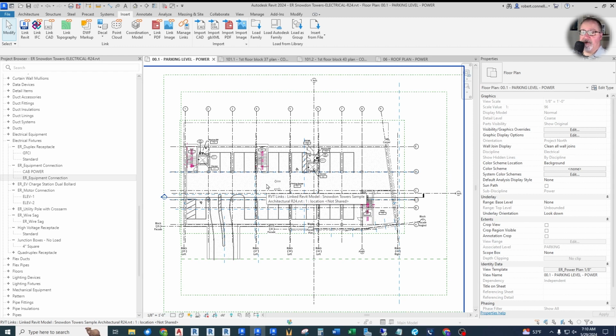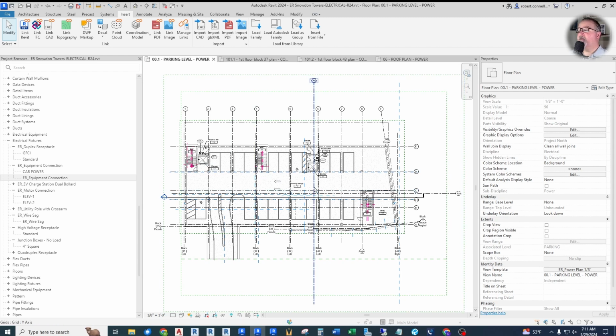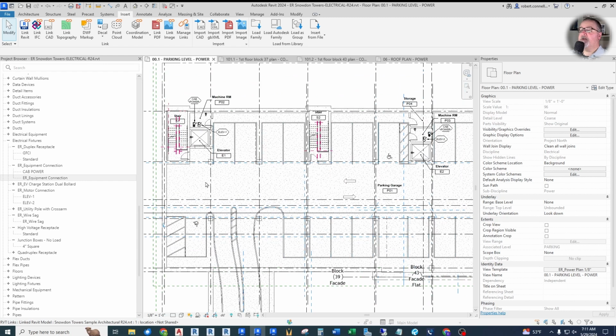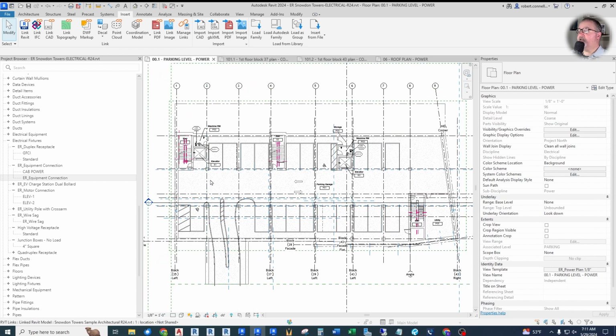Around here, up in the Northwest, they're requiring that we have capacity for 40% of the parking spaces to have the capacity for at least a 32 amp charger, so a 40 amp breaker minimum at 208 single phase. We've had to include those in our projects lately, so we're going to go ahead and put some charging in.